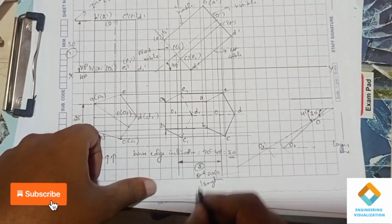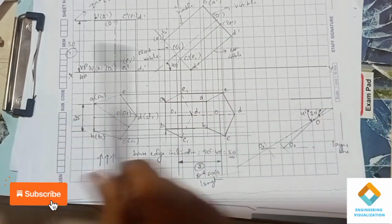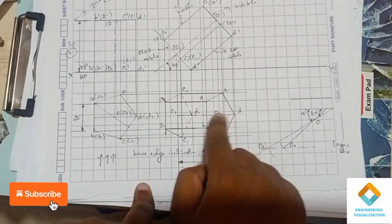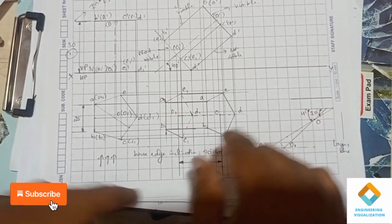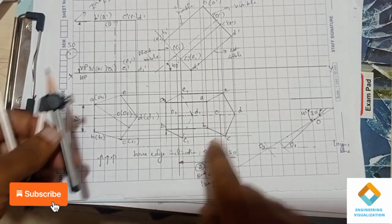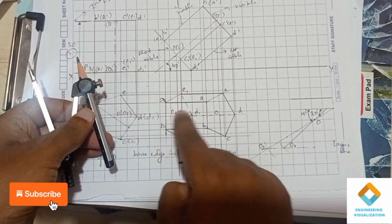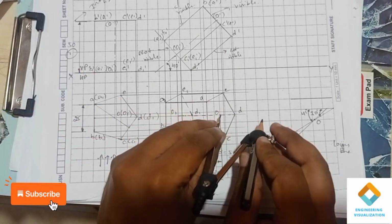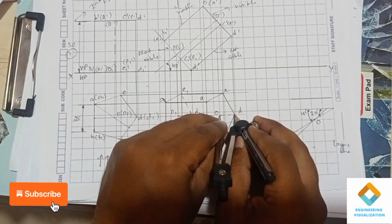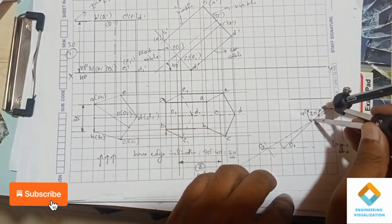Now we need to copy the diagram. This second position top view we need to copy onto O1. Okay, on O1 we have to copy the diagram. Using the compass I'll construct the top face first and then the bottom face. Measure the length using the compass from O to D. O to D and O1 D1 both have the same length, so I'll cut two arcs here.